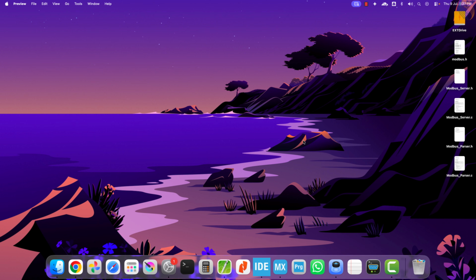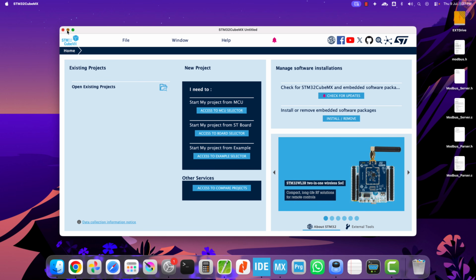So in this first video of the Modbus TCP series, we will see how to configure the STM32 Ethernet peripheral, and how to set up a basic Modbus server. This server will simply respond to a query from the Modbus client. We are not going to handle any function codes yet. We will just send back a basic response, so that we know the server is working correctly. As we move ahead with this series, we will keep adding different function codes to the same project. This means the project will not change, we will keep building on top of it as we go.